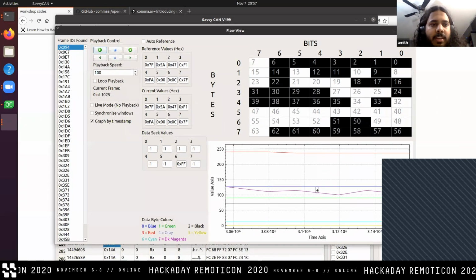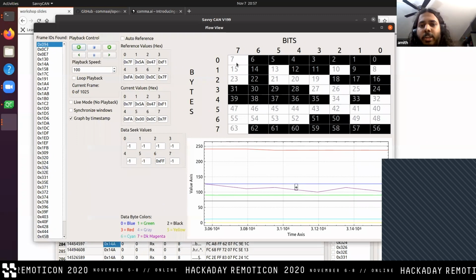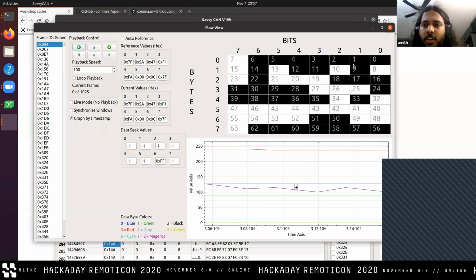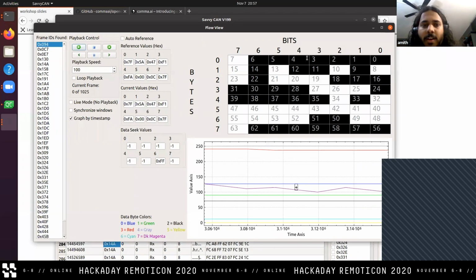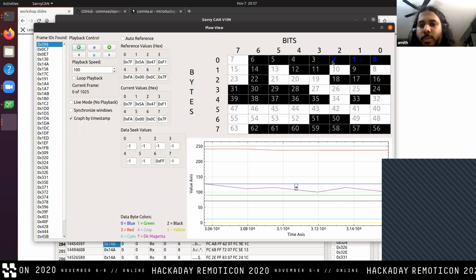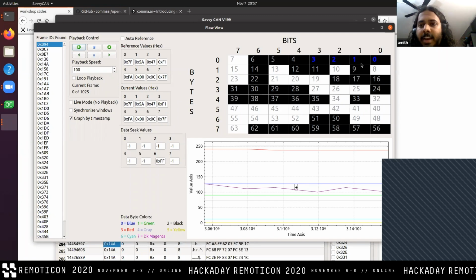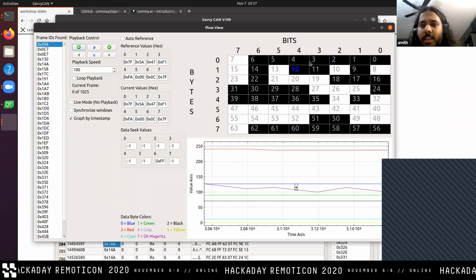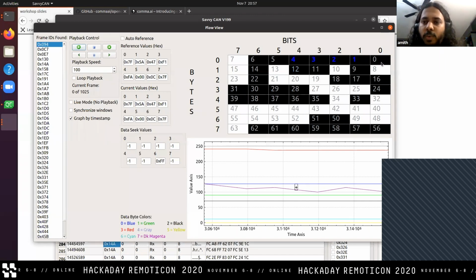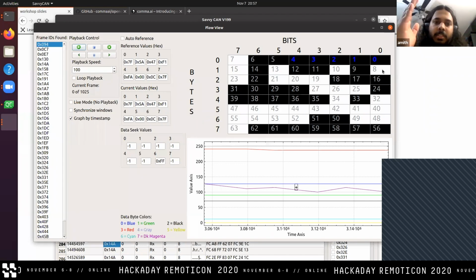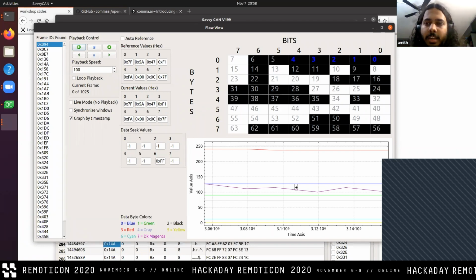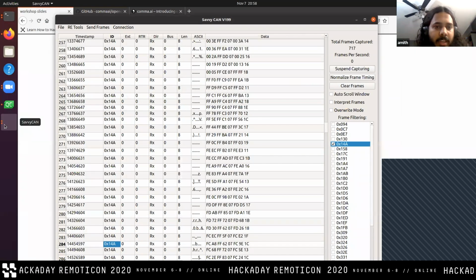So granularity, what it does is, let's say you're looking for a 4-bit signal, and you have a granularity of 1. It starts on the 0th bit of the message. Then it tests for a signal from here, 1, 2, 3, 4. Then it moves up 1, and if it doesn't find anything, it moves up 1 again. So we're looking for 16 bits, so it's going to move the 16 bits up by 1 bit every time. So obviously, the smaller your granularity is, the longer it will take.